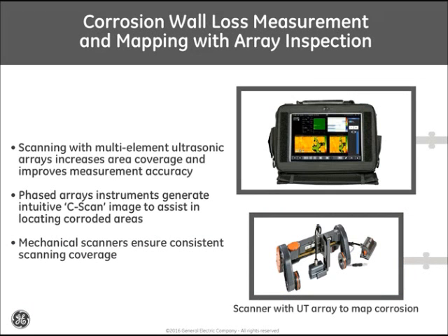On the next slide, we go to the next level of ultrasonic thickness corrosion mapping, where we use array technology to essentially allow us to paint the surface of the suspect area with a wide area array probe. Moving from a single element probe used with a handheld thickness gauge to an array probe is like going from a hand paintbrush to a roller brush when you paint a wall in your house. By using a wide area scan with an array probe, we can essentially display these thickness measurements as a real-time, easily interpretable corrosion map.